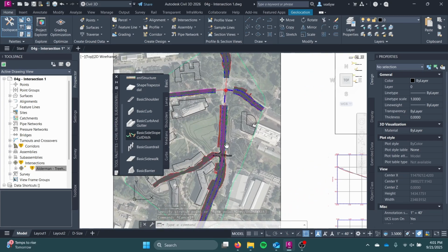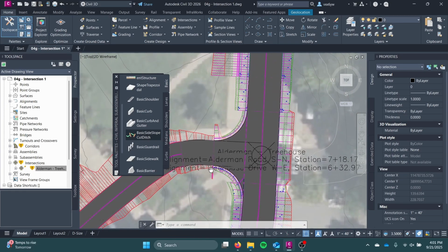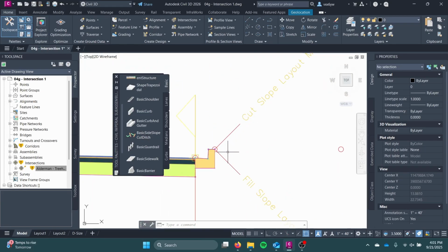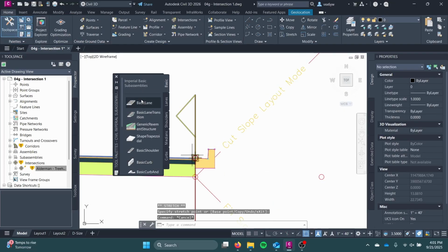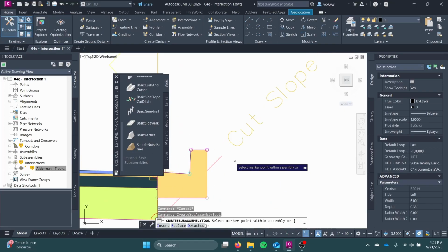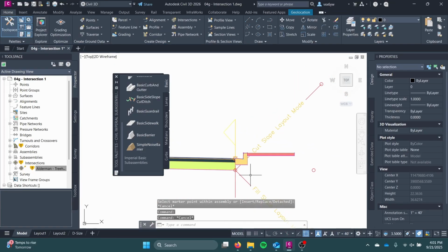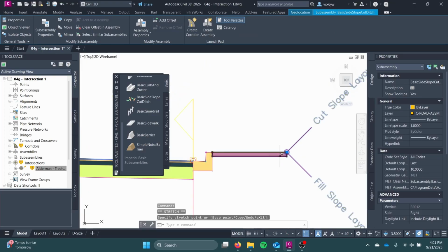Do I also want a sidewalk on that though? Yeah, let's go ahead and make a sidewalk on that too. Why not? So I'm going to actually move this back and then find my basic sidewalk, put it on with 6 foot width, and then drag this back. All right, so now that I've done that,